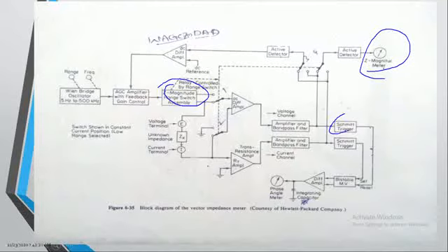So these two Schmitt triggers take the responsibility to convert the sine wave into the square wave, from the waveform coming from this particular element as well as the waveform coming from this particular element. And there are two square waves, and I'm using the digital phase sensitive detector. We have two types of phase detectors to calculate the phase difference: one is an analog phase detector and the other a digital phase detector. We are interested to use the digital phase detector over here.